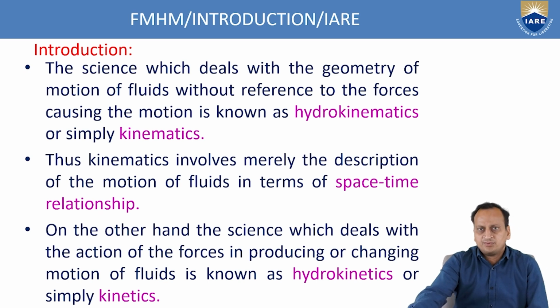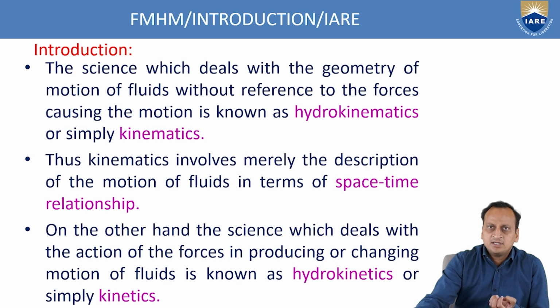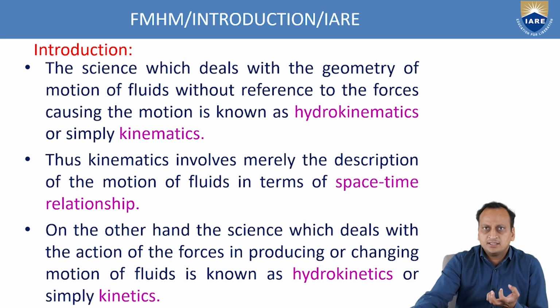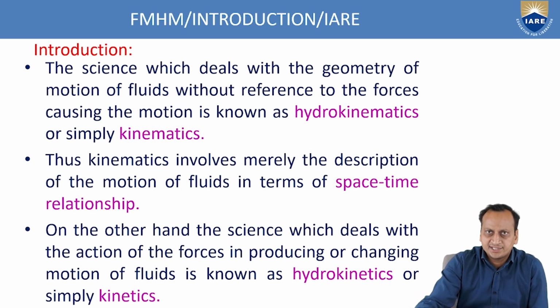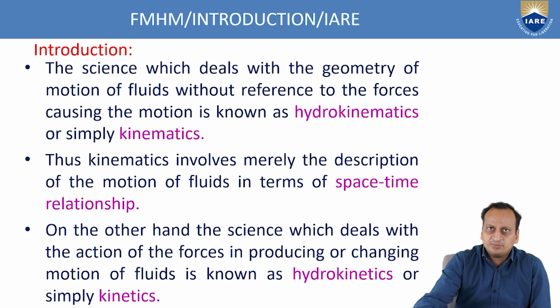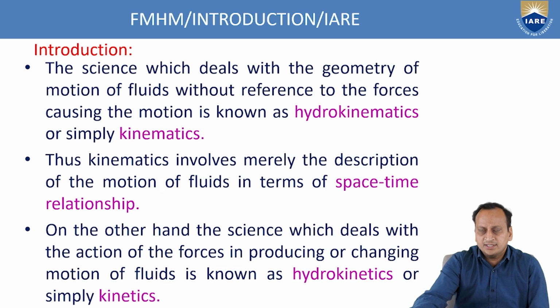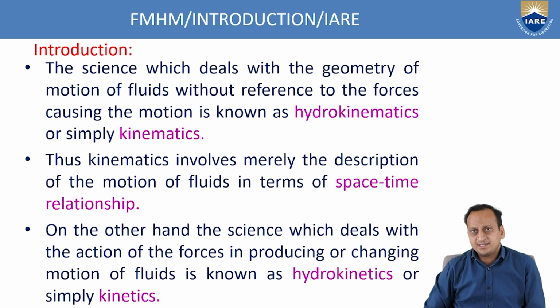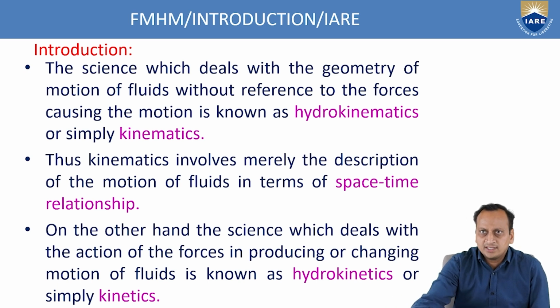That means the fluid flow will be taking place, but we don't regard the various forces causing its motion, like pressure forces, viscous forces, gravitational forces, inertia forces, etc. We don't regard all these forces which are causing the motion of a fluid, but we will study the characteristics of the fluid. Such a study is known as fluid kinematics. Thus, kinematics involves merely the description of the motion of fluids in terms of space-time relationship.